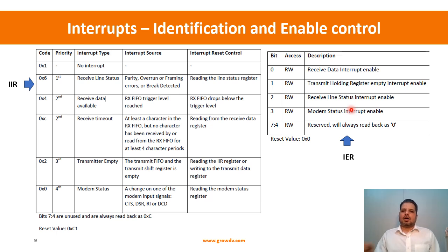And so what happens is there are two things. One, the IRQ pin should get asserted to the processor. That is the first thing. And second, when the IRQ gets asserted, the processor needs to know which condition has led to the interrupt. The way the processor figures it out is by reading the IIR register, and reading the IIR register is what helps us identify the interrupt condition.